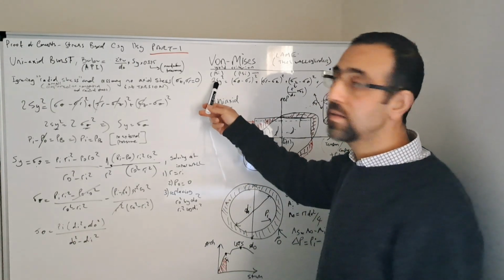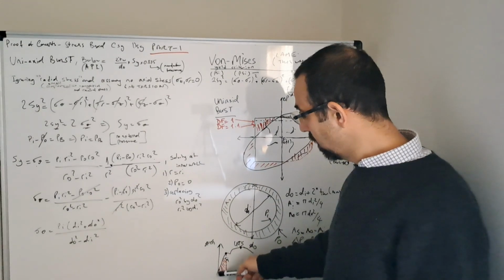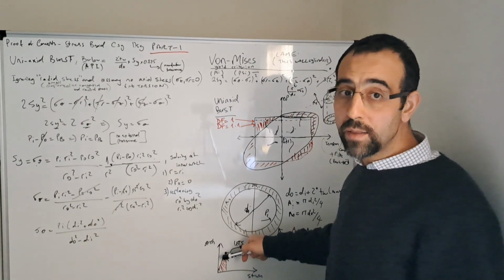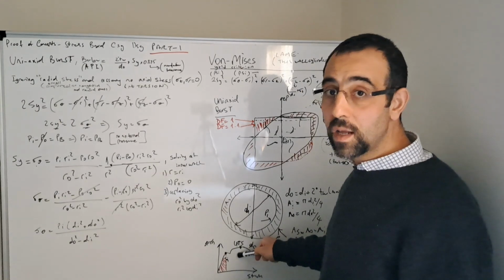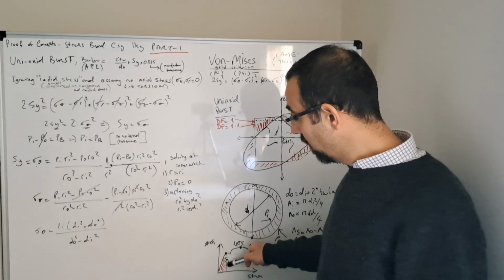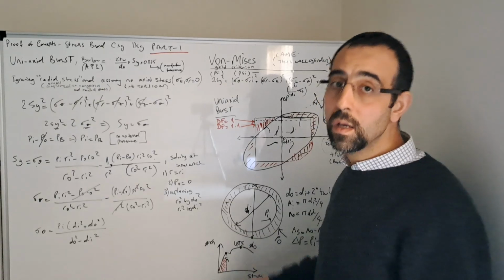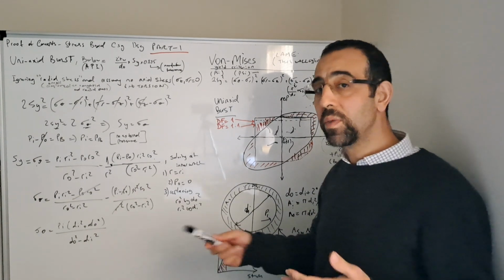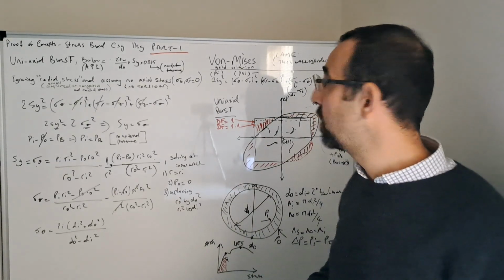So the left-hand side is the yield strength, which is basically the end of this elastic region. It's not the ultimate tensile strength, which is quite a bit higher. We are interested in the yield strength. For example, for L80 pipe or N80 pipe it is 80,000 psi. For P110 it is 110,000 psi.